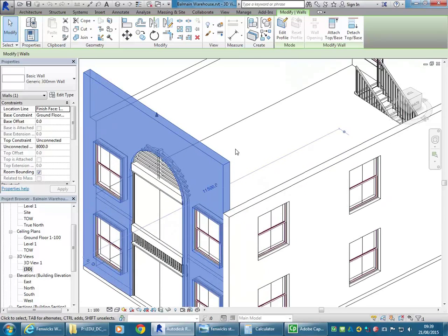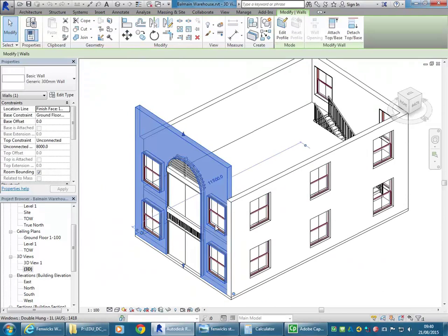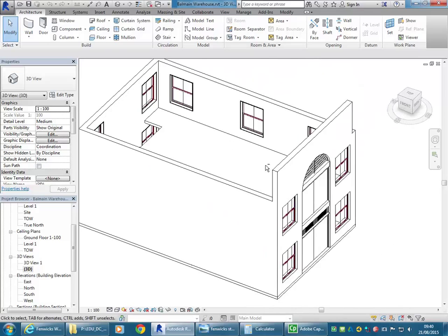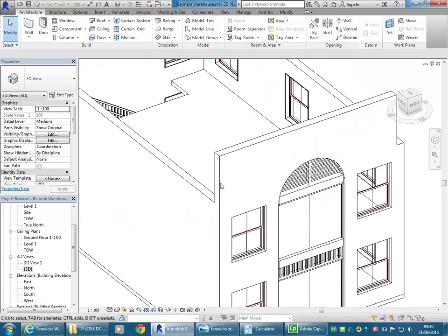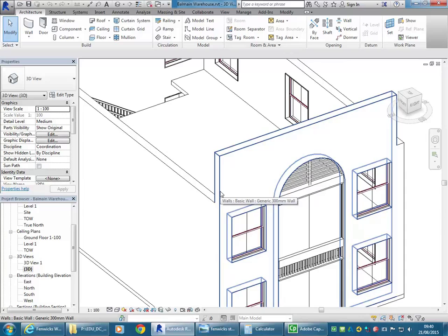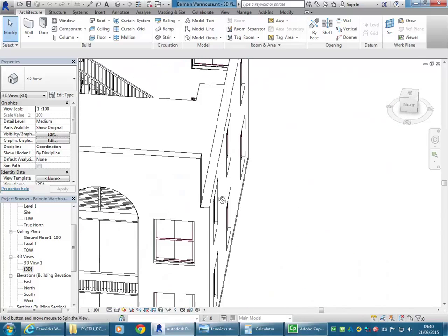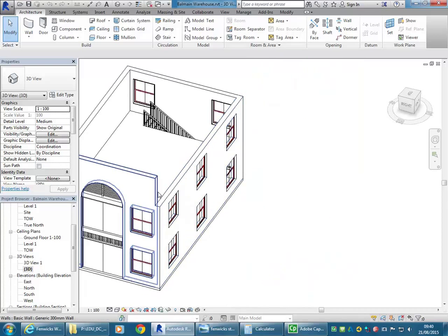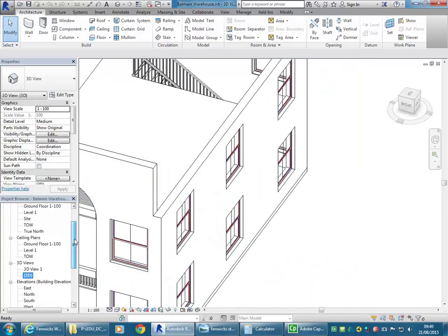And when you create the wall in Revit to give it this raised section, by default it will come up the way that it's showing there. So you can see here we've got the wall joining on the left with that front wall extending all the way to the corner, but on the right it stops on the inside face of this side wall. And that's normal. It's all to do with the direction that you draw the wall.